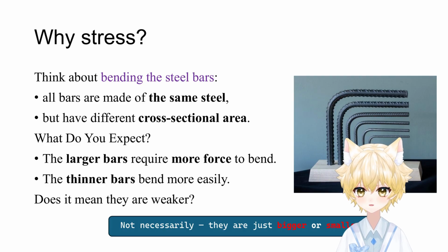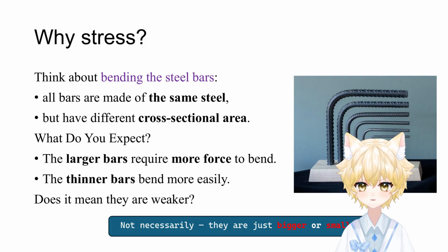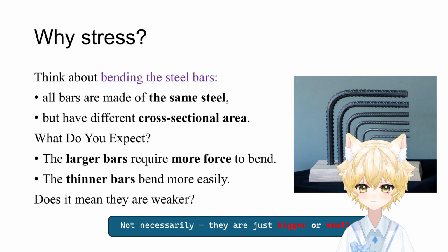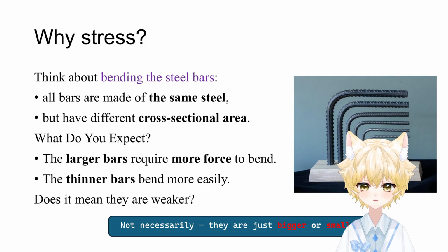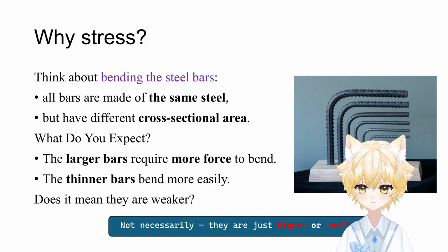So here is the key question. Does that mean the thinner bar is weaker? Not necessarily, right? The difference comes from size, not from the material itself. Force depends on how much material you have, so force alone cannot tell us how the material behaves.